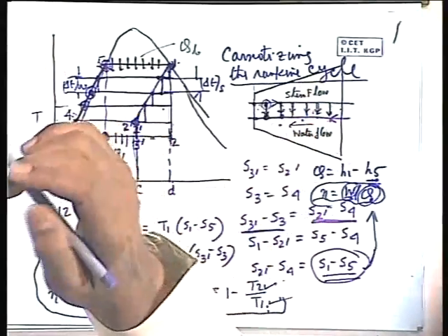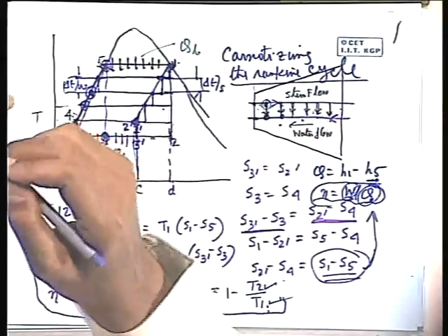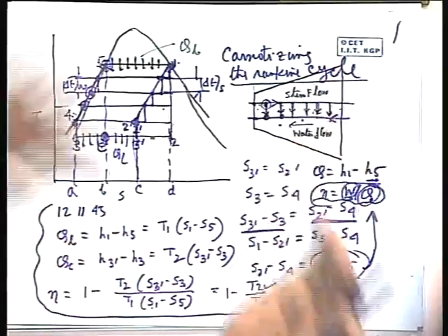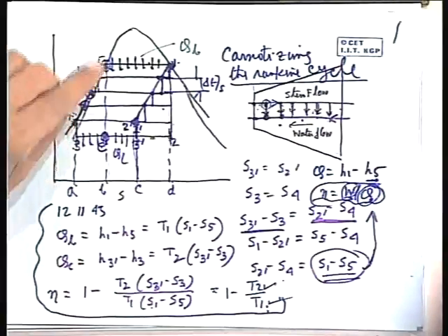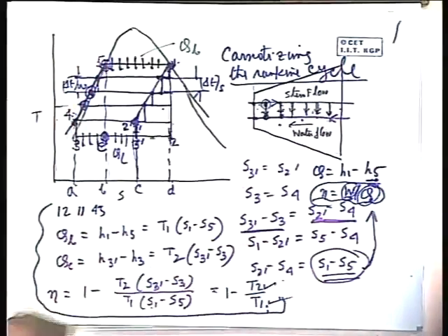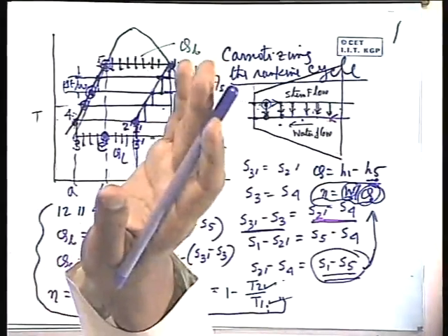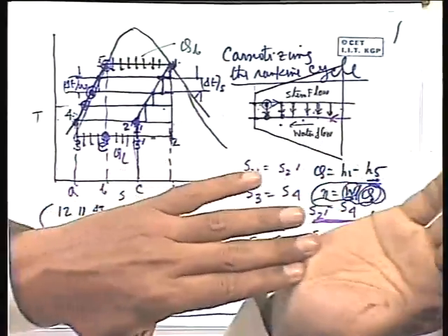You understand? Okay. So the maximum gain, we go to the Carnot cycle. If you can heat up to the 5 point, that means the entire sensible heating is done by the internal heat. So that external heat addition is taking place only to change the phase. That means at constant temperature, which is equivalent to a Carnot cycle. Clear? Concept is clear? Okay, thank you.